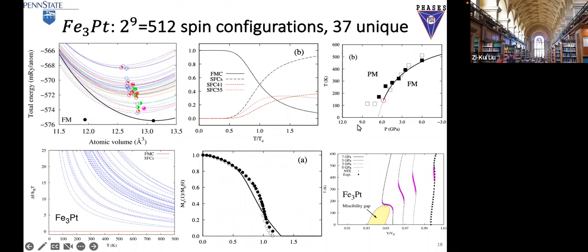And then now if you change the pressure and volume, you get this blue range here, which is negative thermal expansion. The lines are for different pressures. You put them together, and you see there's a band here where you get negative thermal expansion. The reason is that there are metastable states whose volumes are smaller than your ground state. Even though each of them has positive thermal expansion, when put together, the macroscopic volume could decrease at a certain pressure and temperature range.